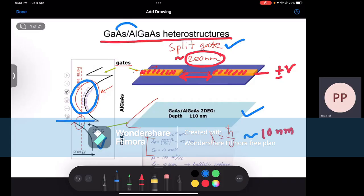So this is also how you can make a field effect transistor out of a 2DEG, right? One single gate that cuts all the way across. Of course, you need to connect the front region and the back region of the 2DEG to some charge reservoir, so charge can come and go.